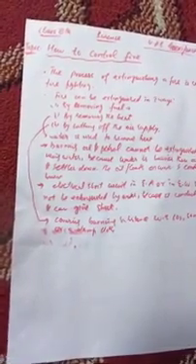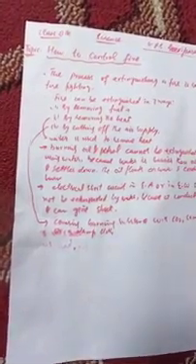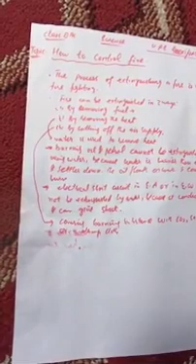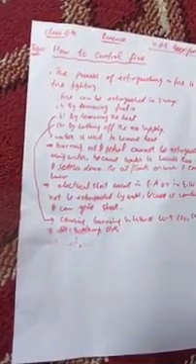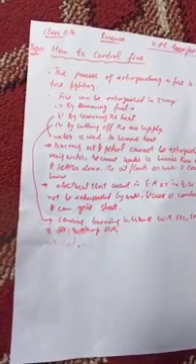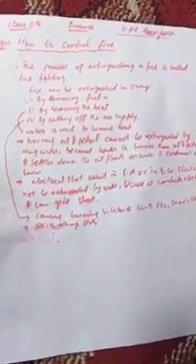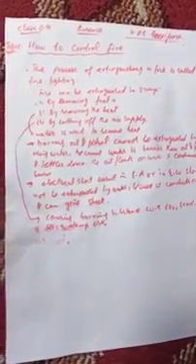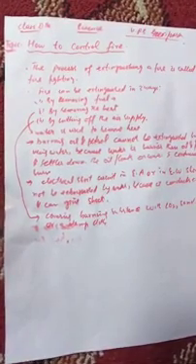There are many advantages of using carbon dioxide. Carbon dioxide is denser than air and forms a layer around the burning substance. It covers the fire like a blanket, due to which fresh air cannot reach the burning substance. The burning substance does not get oxygen from the air and hence stops burning. Carbon dioxide gas neither burns itself nor supports burning, and it also does not harm the electrical equipment.